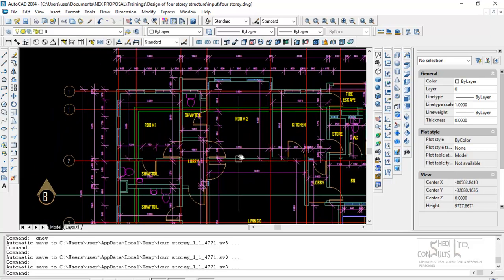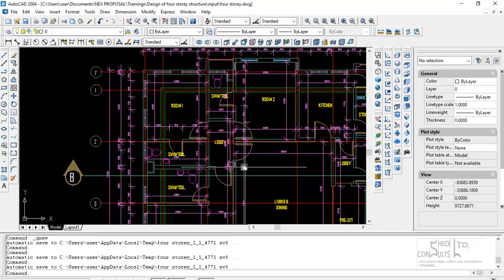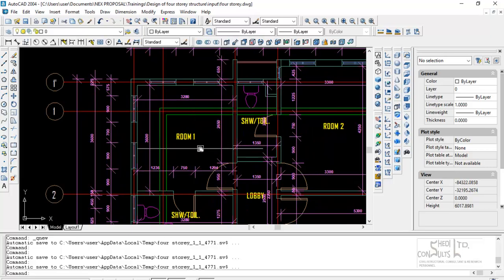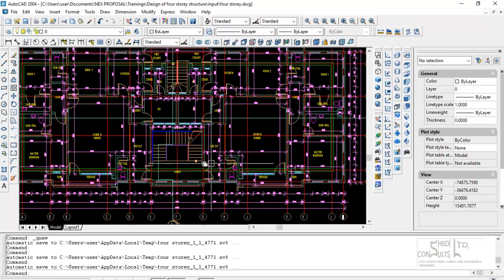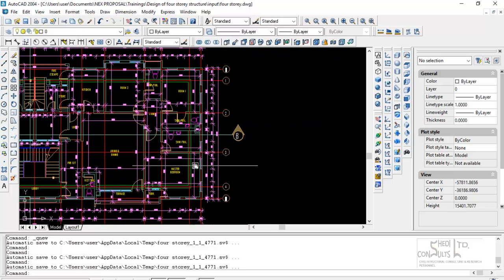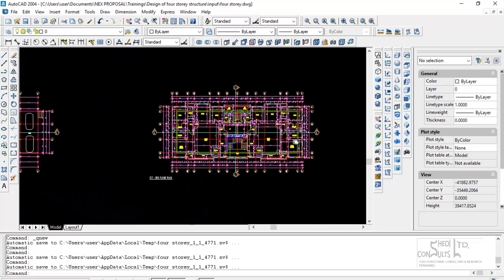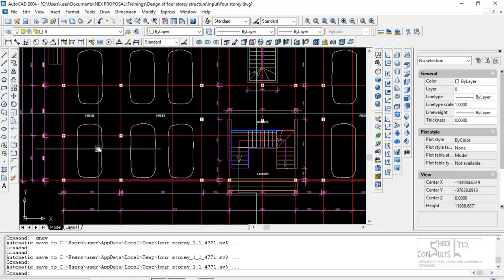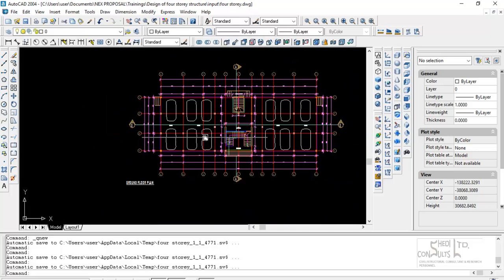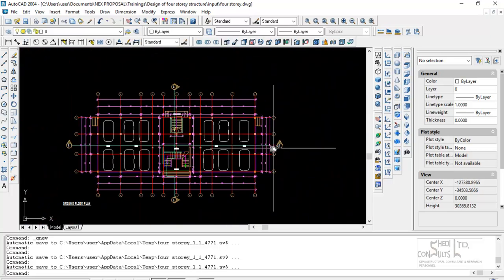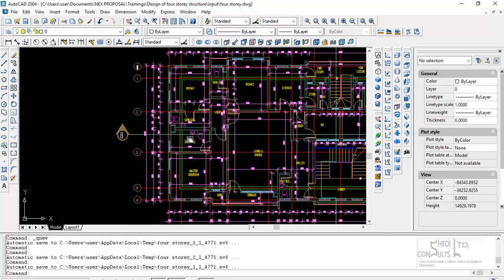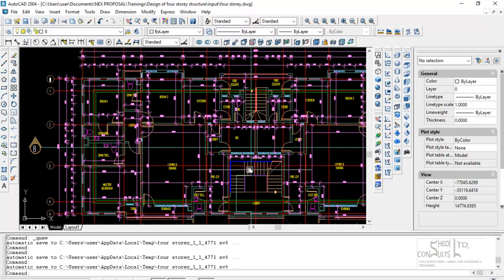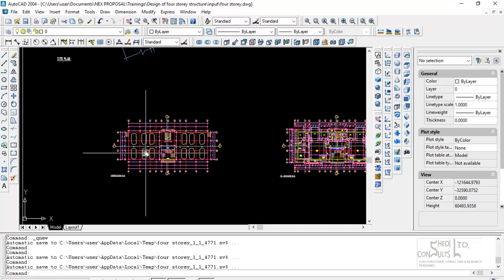The report will contain certain in situ tests and laboratory test results to classify the soil and obtain its index properties. Index properties of an in situ soil are properties that are indicative of the engineering characteristics of the soil. As a structural or civil engineer, you need to establish the engineering properties of the soil and classify the nature of the soil present on site so as to calculate the ultimate bearing capacity of the soil, because your structure is going to be sending forces down to the bearing